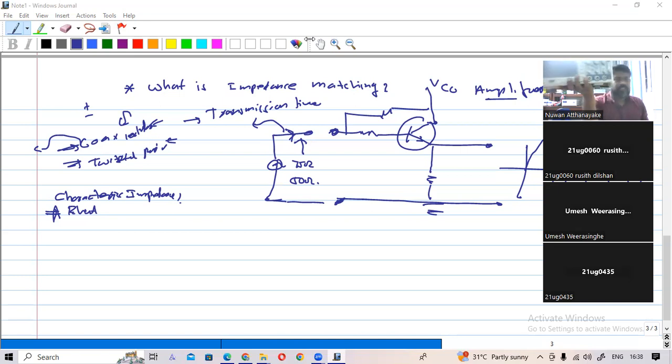But you can change to high impedance in the signal generator, okay? So maybe you can check them once you are at the lab. What I want to tell you is that this is not just a port like the power supply. We are using a transmission line to give the signal. So for a circuit also we have to use it.